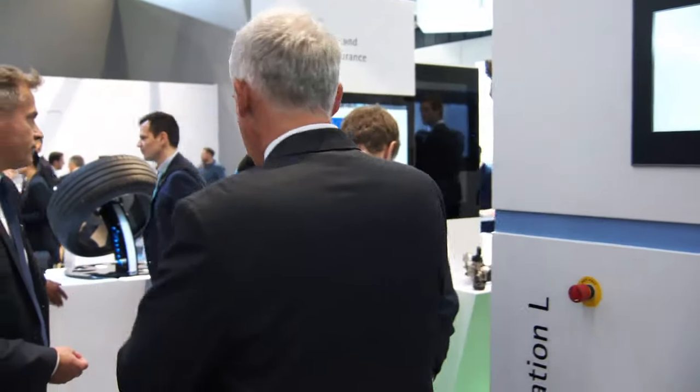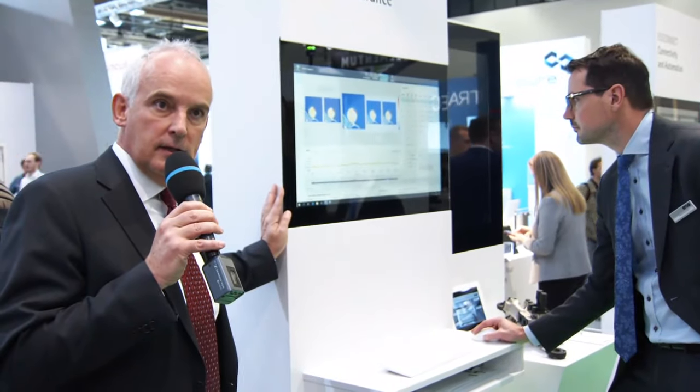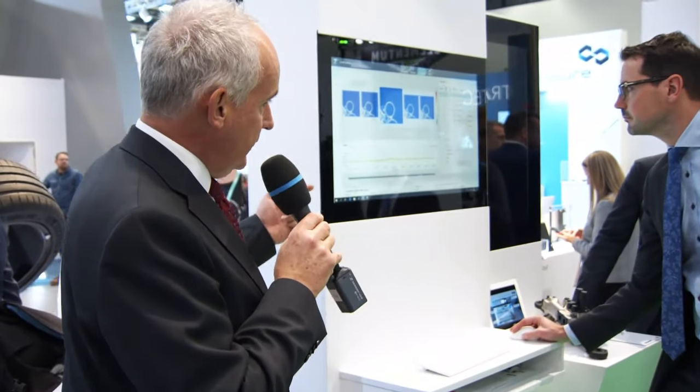And then what we want to show here is especially EOS State Exposure OT, our optical tomography monitoring solution, which is giving you insights into each layer in terms of if you have overheating, underheating, or other kinds of problems which could add up in higher layers. So through watching each of the layers and getting the relevant information, you get a very good insight if your part was printed very well, and even through 3D visualization.